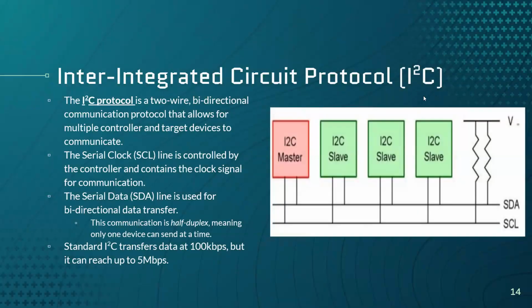Here we go. So this is a popular communication protocol. This is one of the first of the examples that we're going to do. In this case, the bus is actually 2 wires. And it's a bidirectional communication protocol. So that means on the bus, we can have one device talking to another device, while also having that device talk to the other. So in this case, the SDA and SCL, SDA means serial data, SCL means serial clock.